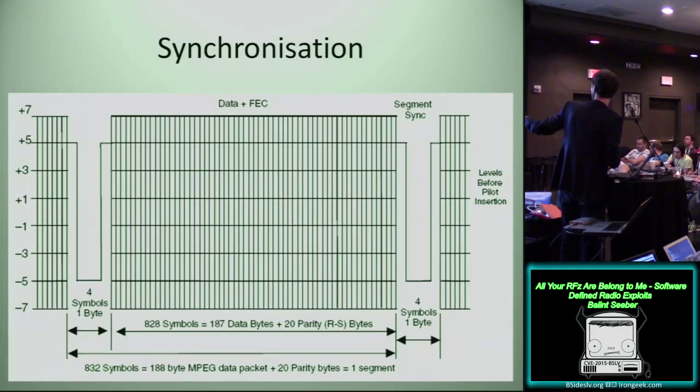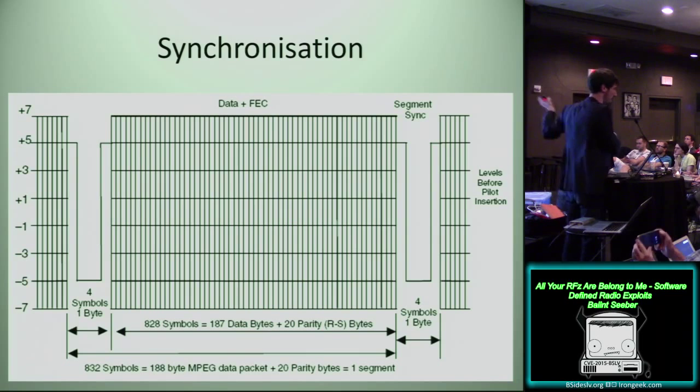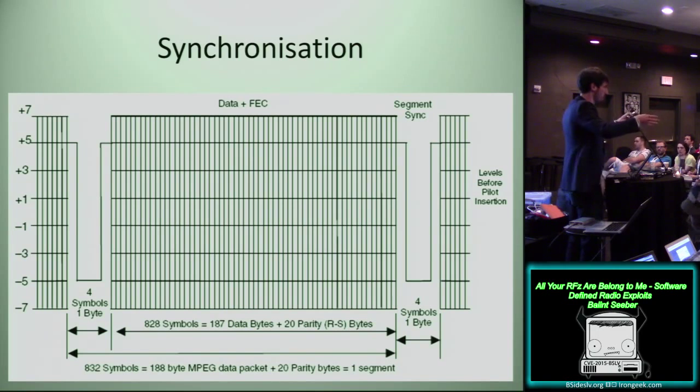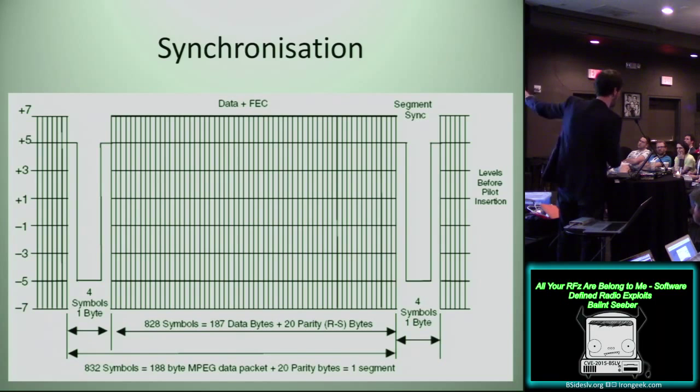And that's how you map them to binary symbols. Now, as your ATSC signals are transmitted, you get all your data sent, but every so often you need to send a known repeating sequence. Remember how I mentioned that with the autocorrelation? For digital television, you have to have this known sequence because your TV sets have to know how to recognize a digital TV signal. It has to have a known sequence that is defined in the standard. So if it says, oh, this is going to be this long sequence, I can lock onto it. This is going to be the beginning of the stream from this point, and I'm just going to keep receiving from there.